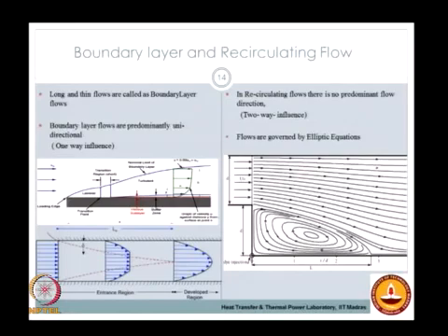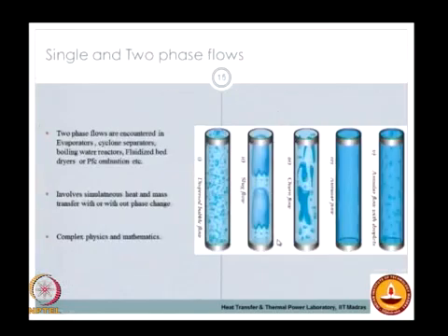corner here. So if you look at two kinds of wall bounded flows, one is where your boundary layer theory can be used, such as in this case, and the other is the recirculating case where the boundary layer loses meaning once the flow separates and recirculates.